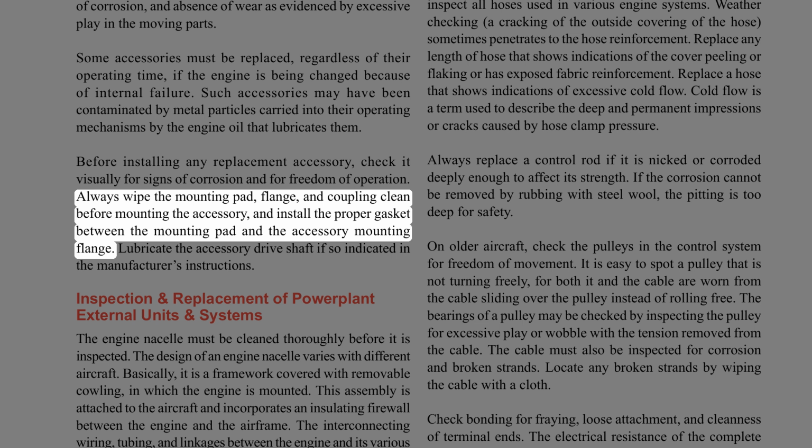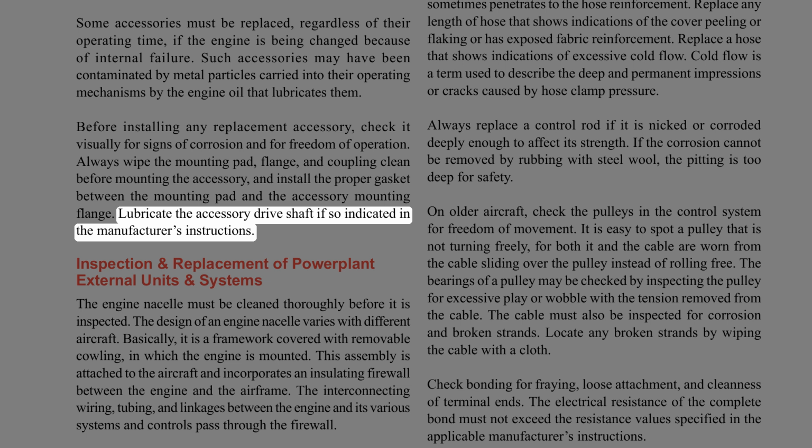Always wipe the mounting pad, flange, and coupling clean before mounting the accessory, and install the proper gasket between the mounting pad and the accessory mounting flange. Lubricate the accessory drive shaft if so indicated in the manufacturer's instructions.